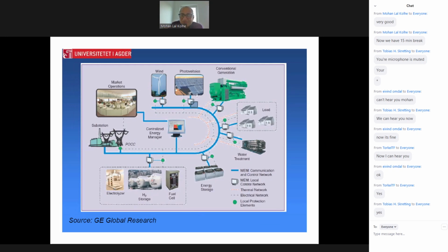Another point he is also going to discuss here: we have the variable source, right? With the variable source, the power output is going to be changing all the time due to the variation in solar radiation. Therefore the maximum power point is also going to change. That maximum power point is going to be managed through the DC to DC converter here. So when we are managing that DC to DC power converter, the operational voltage and the operational current are going to change due to the input into the solar photovoltaic.